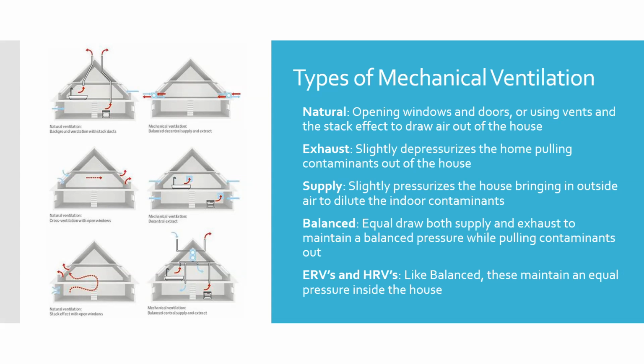Supply only. Normally, you pressurize the house, it blows a little bit of air to the outside, and it kind of blows air into the walls or through those leaks. You're losing a little bit of conditioned air, but you're not sucking humidity and temperature through the walls and through the leaks inside the building's envelope. You're actually pulling a little bit of air from outside into the building. It pressurizes it and pushes it through the wall. It consists of a fan and a duct system.